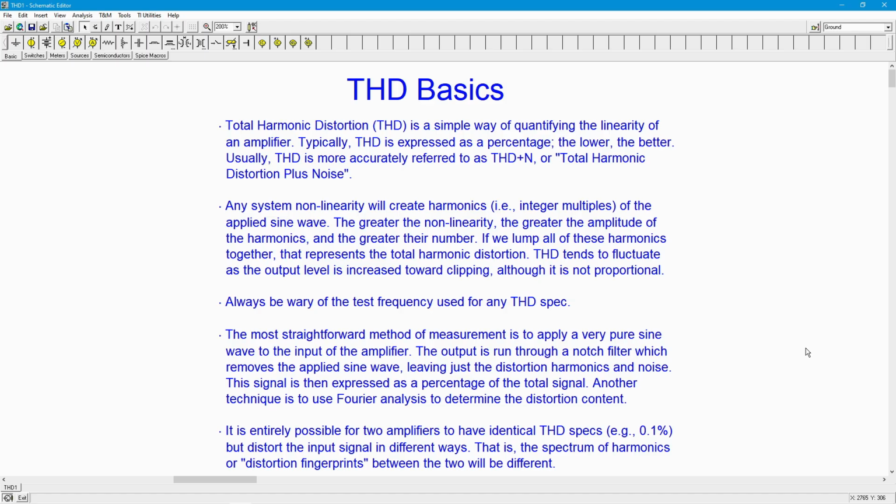In other words, all you had to do was manually get the filter coarsely tuned to where you wanted it. And the circuitry inside was smart enough, so to speak, to determine the exact frequency and slightly alter its own tuning to give you the best result, to completely null out that input frequency. Then it would send that signal off to an RMS reading meter, and you'd have your percentage. It was that simple.